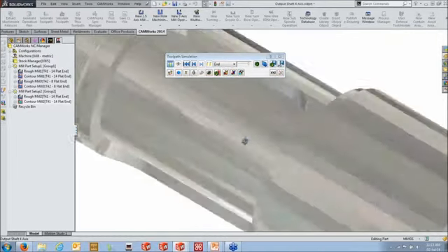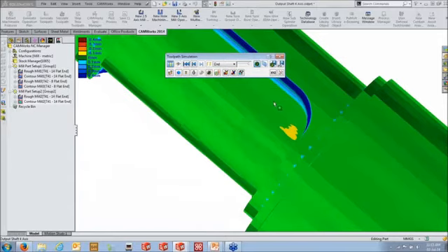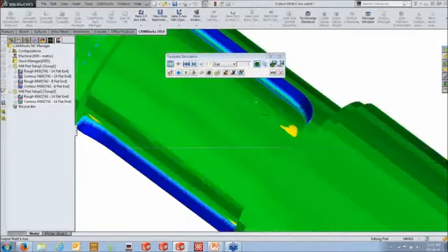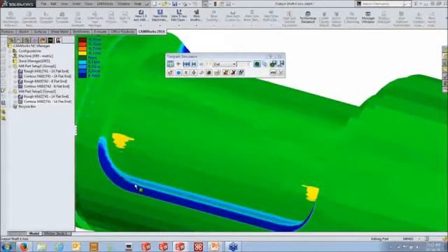So you can see down here, check on the geometry here, make sure it looks pretty close. Now, we do have some material left over here, and one of the biggest questions I always face is, how do I remove that material? Well, a lot of the time it's dependent on the geometry used to create the toolpath.